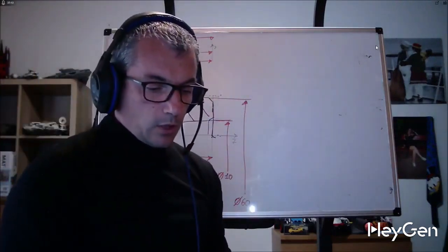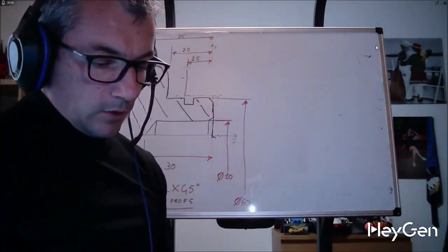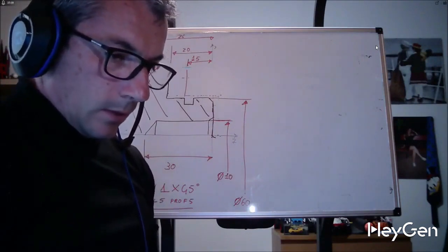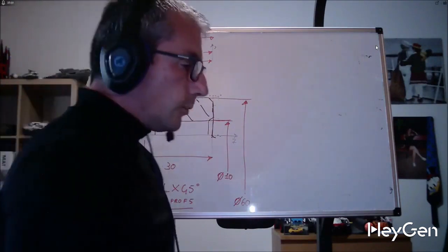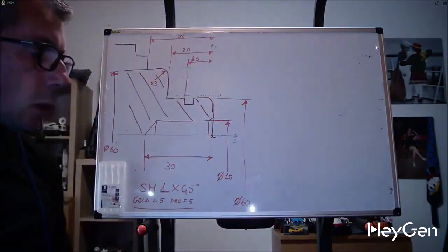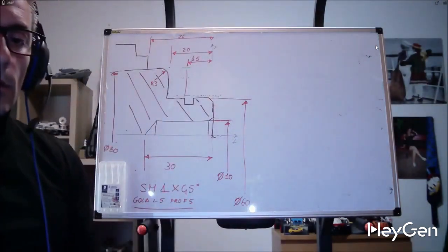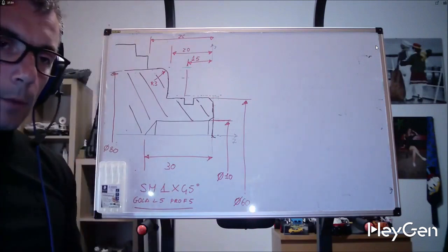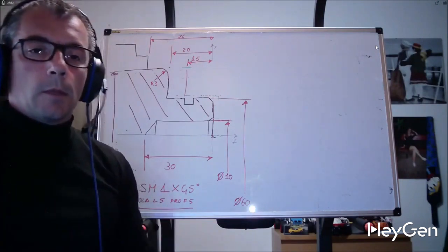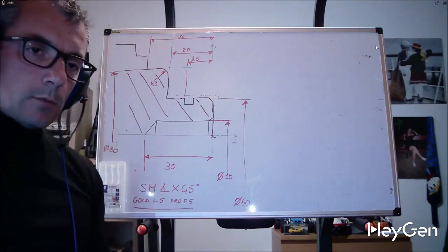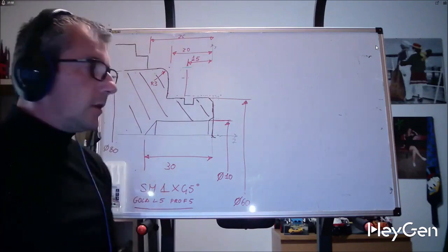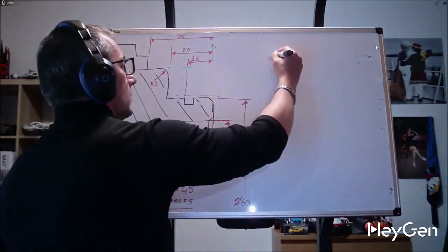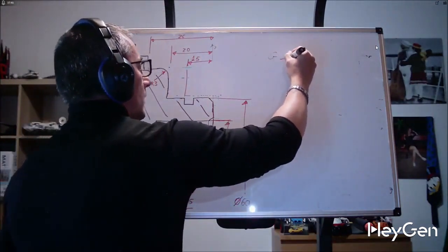Roughing, long axial roughing, drilling with chip breaker, cycle for front grooves, radial grooves, threading. I would say that fortunately these cycles are better oriented, a bit of everything. So now remember that our programs will become a sequence of X and Z, alternating between fixed cycles and X and Z. The fixed roughing cycle, for example, is identified by a G that identifies the cycle.